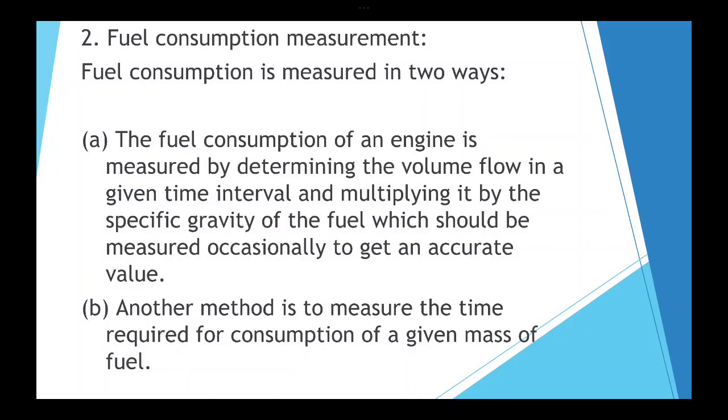Next, we have fuel consumption. It is measured in two ways. The first one is by volume flow. The fuel consumption of an engine is measured by determining the volume flow in a given time interval and multiplying it by the specific gravity of fuel, which should be measured occasionally to get an accurate value.